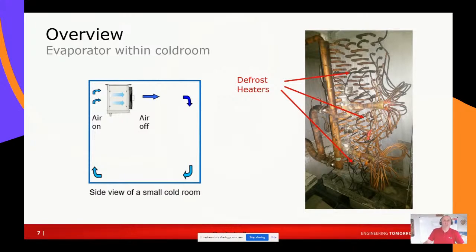But obviously, the most important thing really is to check your suction pressure against where it should be. But if you want a visual indication on your cooler, then the distributor legs are a very good place to go, because you'll get frost and ice build up on those, but you'll get nothing on the coil itself. So that's a good one to look at.